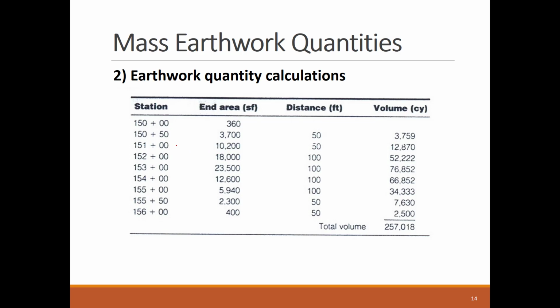Also, you will notice that some segments had a length of 100 feet, like the third segment that is bounded by stations 151 and 152. Probably the project plans didn't have cross-section details for the missing intermediate stations, or the geometry between the stations in this part of the road can be uniform over a longer segment length.